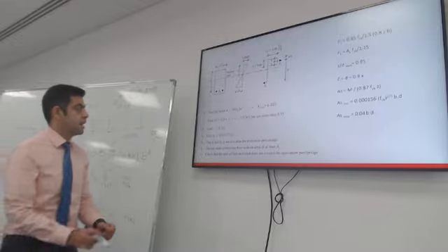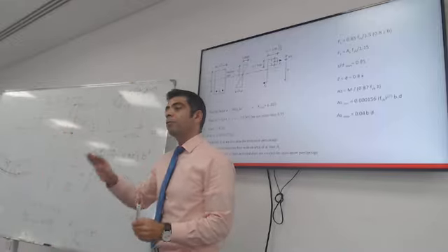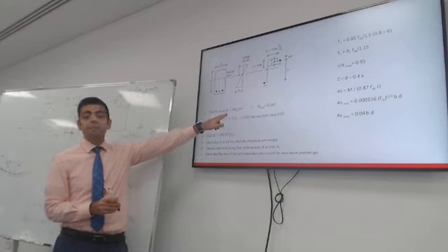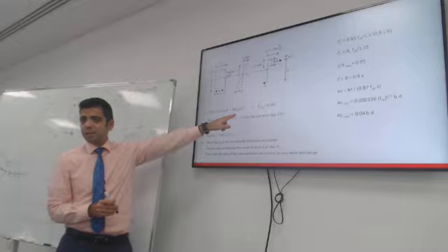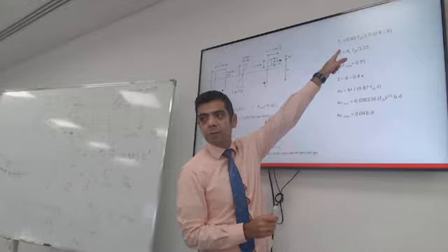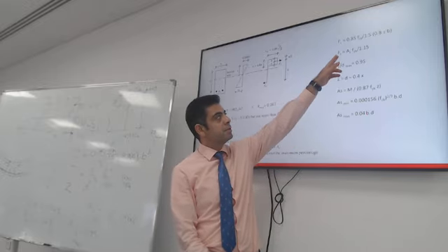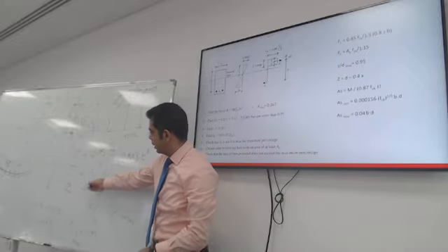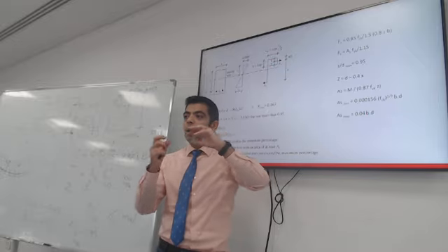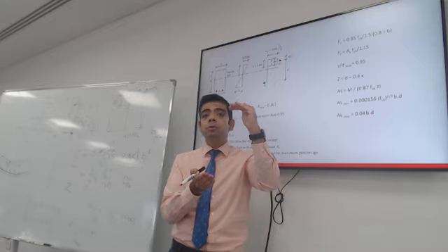So, important step. This step is also reflected in the very first step when you do the analysis. When you run these equations together, this is the compression force, I already got it here. This is the tensile force in the bar, I already got it here. They need to be equal. So I can develop an equation to calculate X, the depth of the neutral axis.